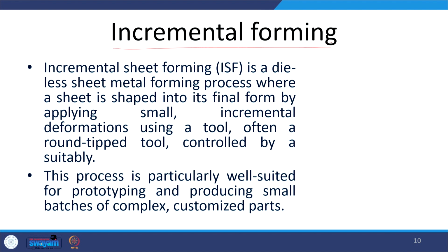Incremental forming is another relatively new advancement in the area of sheet metal forming. So, this is known as incremental sheet metal forming, or ISF. It is a die-less sheet metal forming. It does not use any die or punch, it simply uses a rounded tool, okay, to deform the sheet incrementally. Okay. So, say there is a sheet, it is being held at the ends, and then the tool will be applied, and this is a robotic control or CNC control tool that will be causing the controlled incremental stepwise plastic deformation of the sheet in order to realize the shape desired.